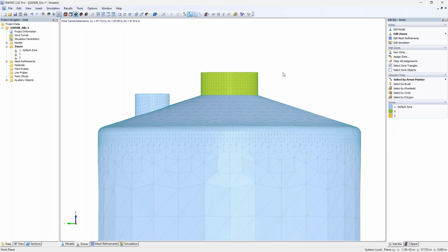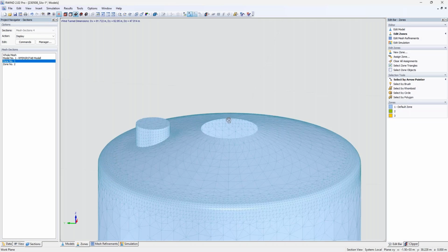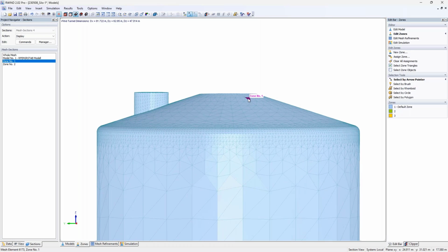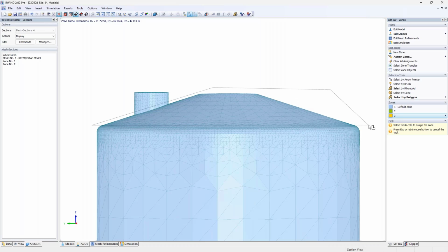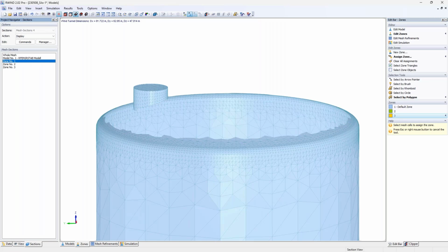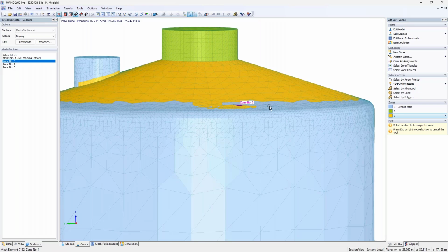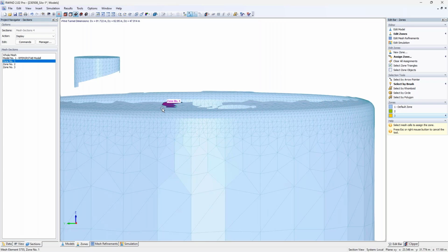So if you have assigned this to the zone, the next good part is that you could now also choose the sections and only display now zone number 1. As you can see, now my top part is gone. So this will also make it easier for me to maybe define a next zone now. If we go to zone 3, you could also choose a polygon and try to define it maybe by certain clicks. Double click at the end. It will then highlight all zones so that you can get a graphical overview, but you can of course once again go back and only display zone number 1 and go on, for example, with the brush by clicking on zone 3, mark elements, see if they are correctly assigned, go once back and so on.